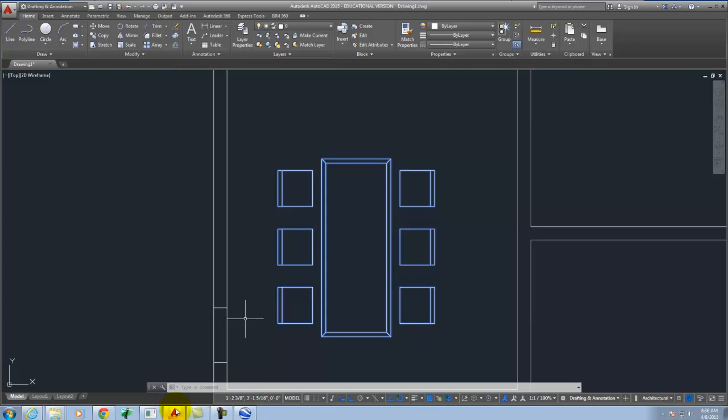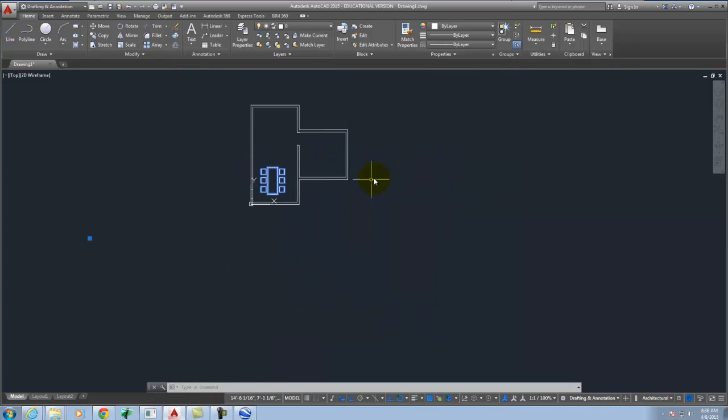So there's a bunch of them out there, and as you start to populate your floor plan, there's no harm in using some pre-made objects, okay? The biggest thing that you'll run into down the road in a studio environment is if you start to use pre-made windows, like exterior windows. Studio heads are going to be saying, why don't you just make your own windows? Why are you limiting yourself to these small pre-made windows? For the scope of what we're doing here, there's nothing wrong with using pre-made windows, so you're more than welcome to do it. But I just wanted to point out that that's an issue down the road. You'll be constraining yourselves from a design perspective if you use pre-made windows.